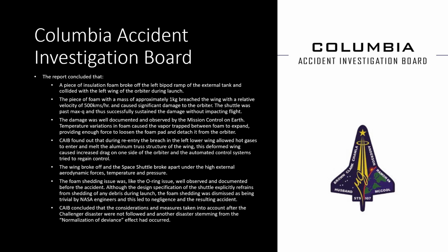The insulation shedding issue was, like the O-ring issue, well observed and documented before the accident. Although the design specification of the shuttle explicitly refrains from any shedding of debris during launch, the foam shedding was dismissed as being trivial by NASA engineers, and this led to the accident of Space Shuttle Columbia. The CAIB also concluded that the consideration and measures taken after the Challenger disaster were not followed, and another disaster stemming from the normalization of deviance effect had occurred.